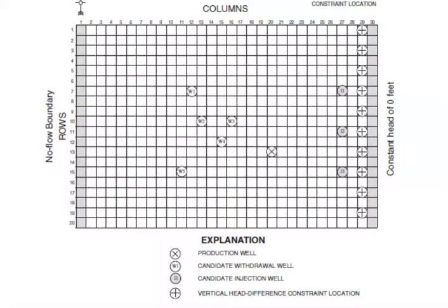Saltwater intrusion is monitored by imposing constraints on head differences along the sea boundary, and can be controlled by the use of injection wells. The overall objective is to maximize the net withdrawal of water, that is the withdrawal from the 5 wells, minus the injection needed to control saltwater intrusion.